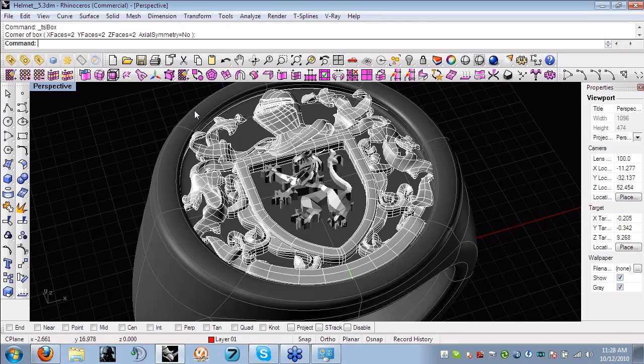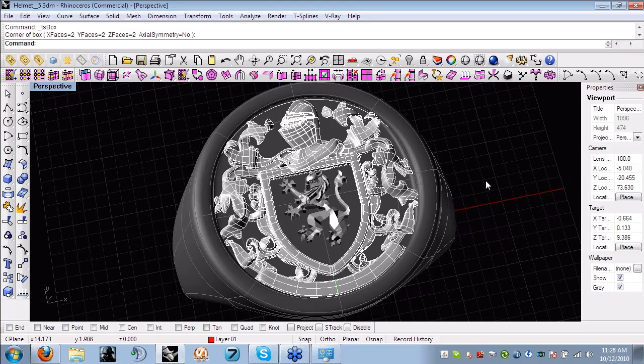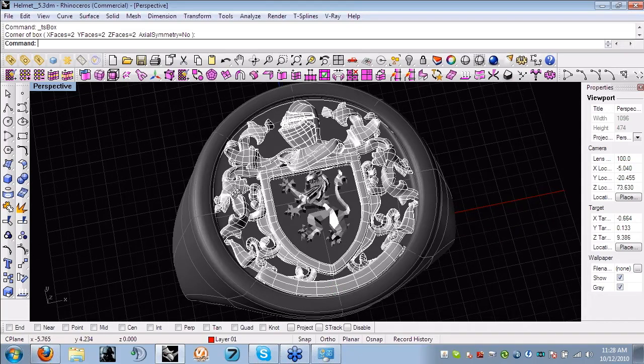And traditionally with standard NURBS models, we've always had a very, very hard time because Rhino likes to make everything in triangles. And so when we transport over to other applications like ZBrush, the triangles are often too heavy, the topology of the model's not right, and it's very difficult to get sculpting nice and perfect like you want in ZBrush without having to do a bunch of workarounds.